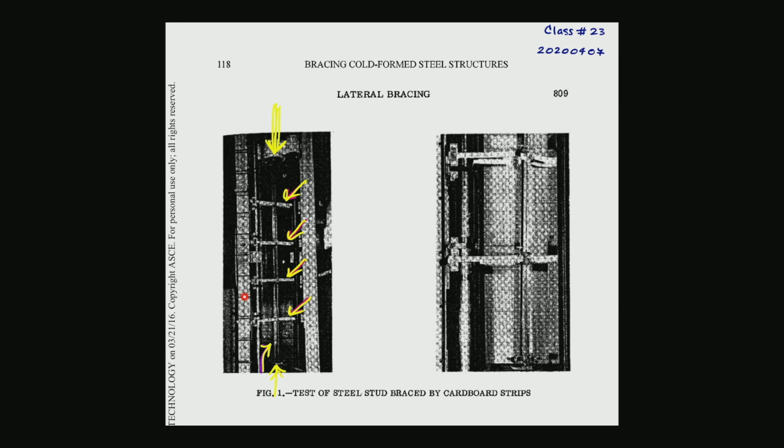So the big frame here is the UTM, Universal Testing Machine, and the center column here is the test specimen. It is a tested column, and the test column is supported at the top and at the bottom by a knife edge hinge that gives you the very accurate boundary condition. This boundary condition only allows rotation about the weak axis, as it is a knife edge, like a line support.